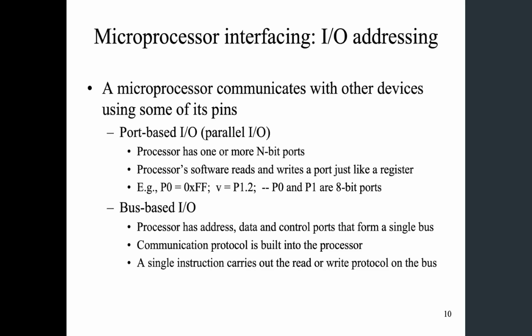The other way to access the ports is to use bus. When we talk about bus, we are talking about addresses and data and the control signals. We can use these buses to read a bus-based I/O device, I/O port. The communication protocol is built into the controller. You really don't have to use the software to emulate the timing diagrams.